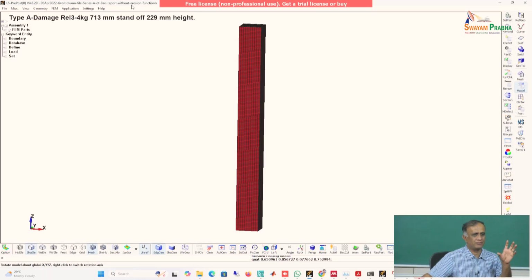If the strain in that element goes to 0.1, let's say, or 1% or 5%, whatever, remove that element. When you remove the element, you are removing the mass also. So removing the mass actually changes, you're inherently changing structural properties or the response. So in a finer mesh, maybe erosions, you're not affecting it so much.